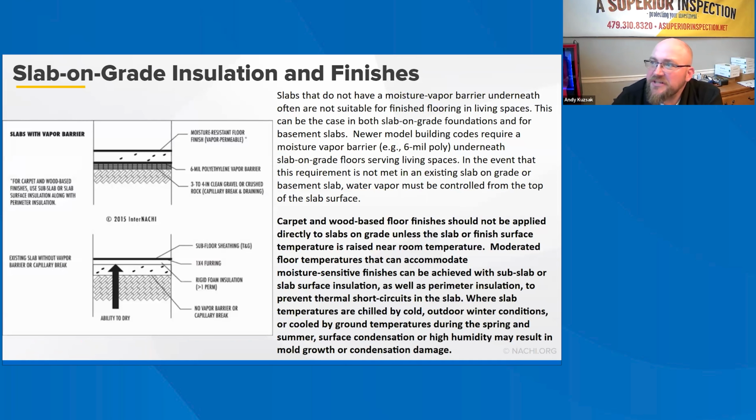Like basement wall finishes, finishes on concrete floor slabs on grade are exposed to a unique environment due to direct ground contact. From a moisture perspective, tile, terrazzo, stained decorative concrete, and other moisture-resistant finishes are ideal for slab on grade construction. These materials are resistant to flooding and other sources of moisture damage and are typical in southern and hot, humid climates. If a slab shows signs of pre-existing moisture problems such as dampness or condensation, salt deposits, standing water, then the issue should be addressed before moving ahead with finished flooring.